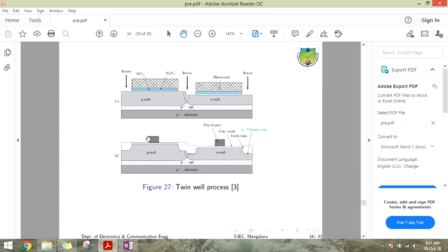After this diffusion process, the silicon nitride and silicon dioxide stack, and the tank oxide, are etched away. Since this tank oxide consumes silicon from the substrate, etching it off leads to a step in the silicon substrate. Next, we form the isolation regions or the field transistors that will guarantee us there is no electrical crosstalk between the adjacent transistors due to interconnection.